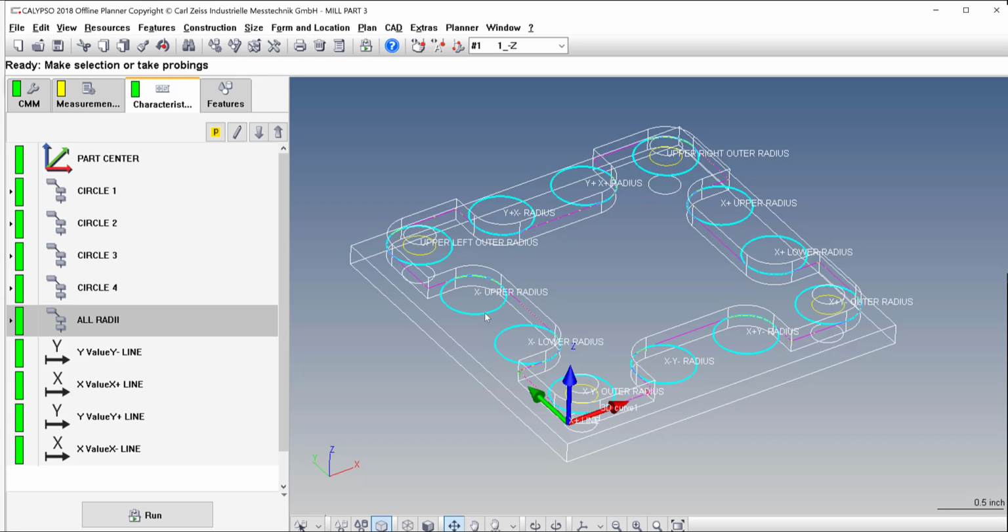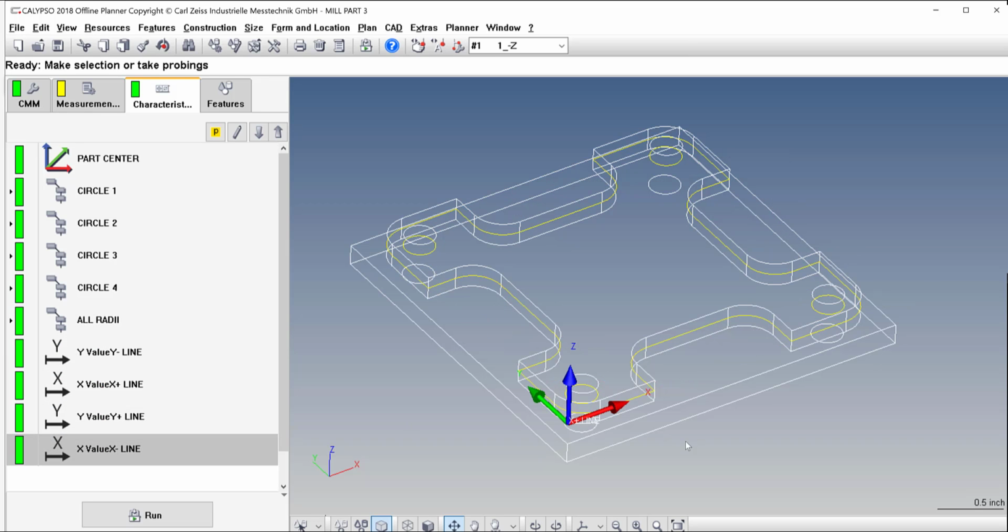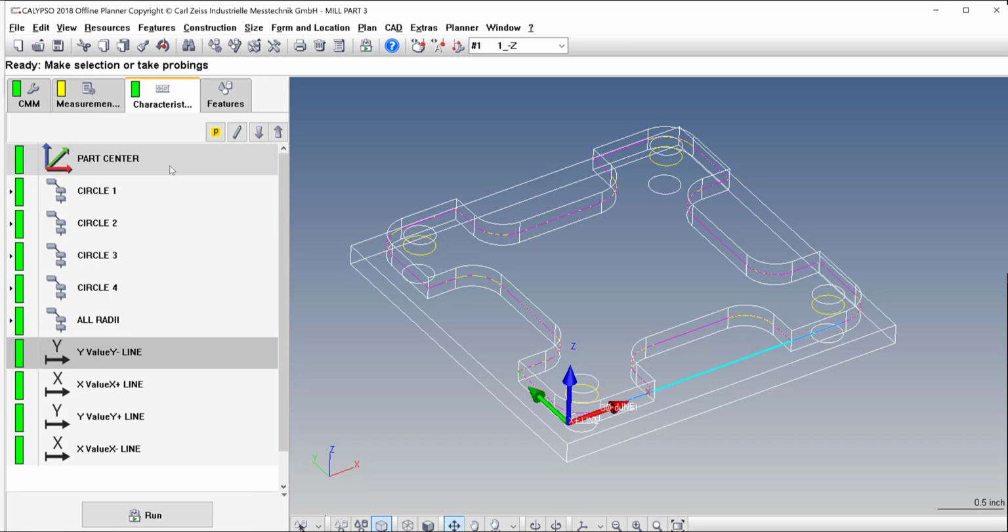Sometimes if you're running these, and since the tolerance is somewhat loose, it doesn't matter. But somebody might ask for that, so there are different ways to interpret things. We're just going to use radii for now. And then we will continue this method of programming it essentially in half. I think that'll definitely make the report cleaner. All right, so I'll put a transition here. I'll continue the widths in the X and Y separately, just like we did for the overalls of the 2 3/4. And then we'll come back in and do caliper distance for the depths.